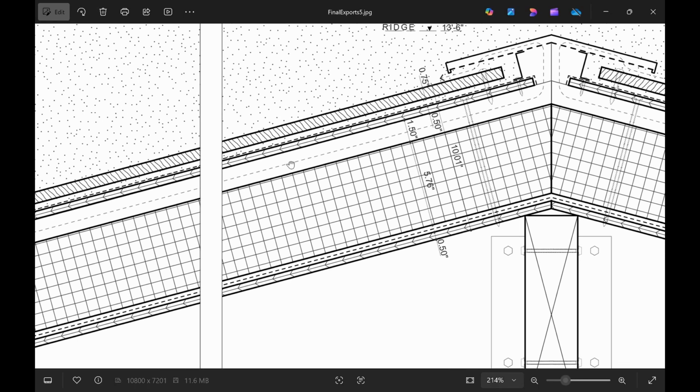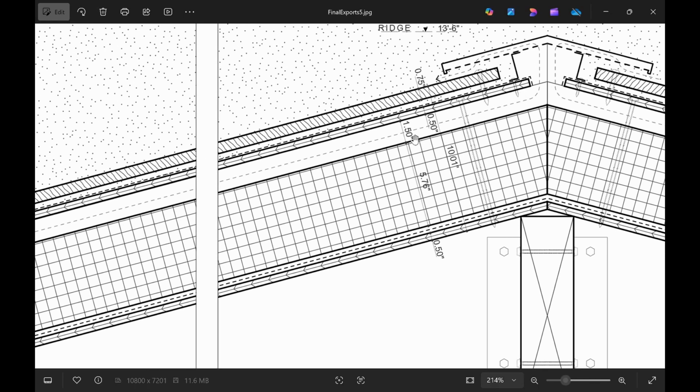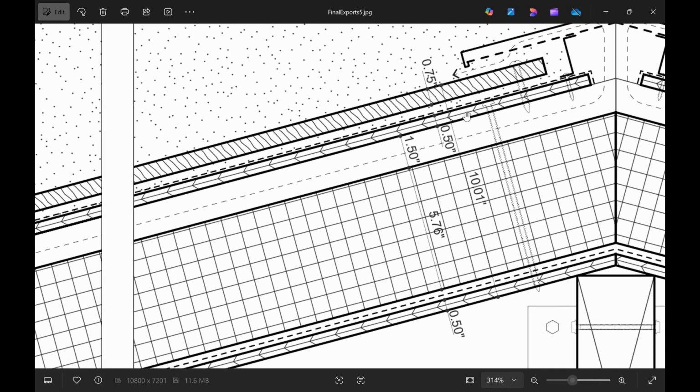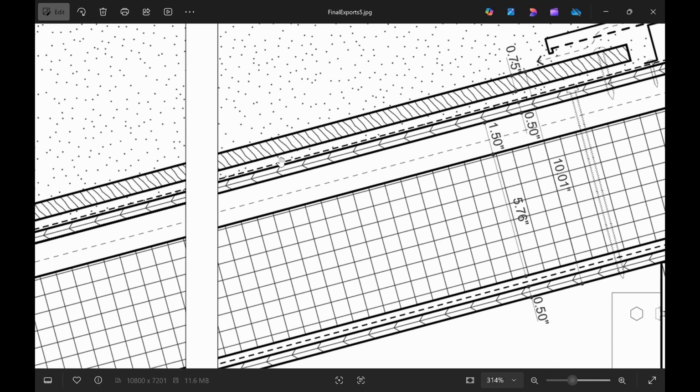This is also going to act like a rain screen. So you're going to have these long battens that go all the way down. And then you're going to have a secondary sheathing element with ice and water shield and your weather barrier as well. Not weather barrier, excuse me. They would call it a drainage mat, or some people would call it a water membrane. People call it different things, but you would need another membrane on top of here, not just here. And then you would have your finished facade over that.